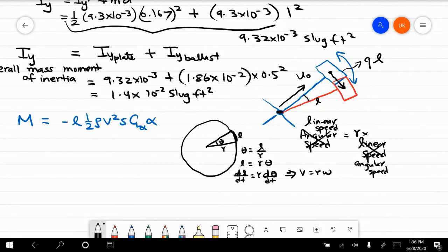That means this angle, which you can think of as the angle of attack, let's call it alpha, the angle between this chord line and the relative wind, that's the angle of attack. And this angle of attack can be related to this qL and U naught. This is a triangle, and in this triangle I can write tan alpha equals qL divided by U naught.